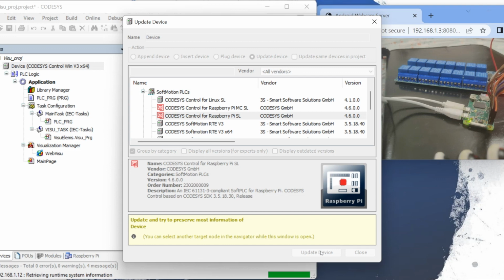Only what changes is the addition or deletion of the IO, which means different hardware will have different kinds of IO. For Raspberry Pi we have the GPIO. For another PLC we will have different kinds of IO, like fieldbus IO, correct? So if you see here, the GPIOs got added, one wire got added. These are the things which we configured in the configuration of Raspberry Pi, so all those things will get enabled. We had to set this in the Raspberry Pi when we were doing the OS configuration.